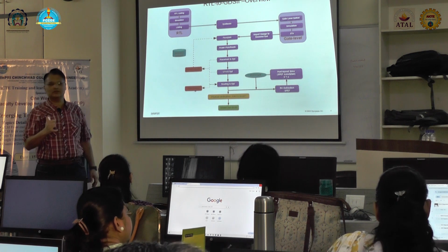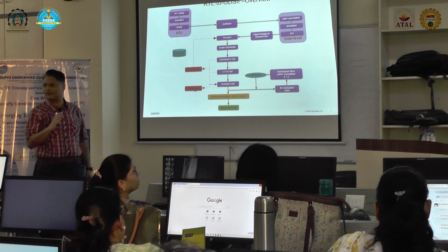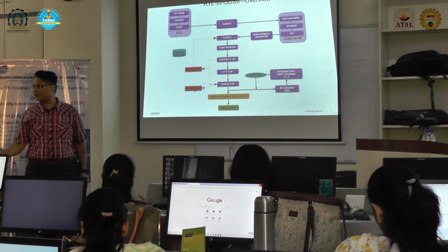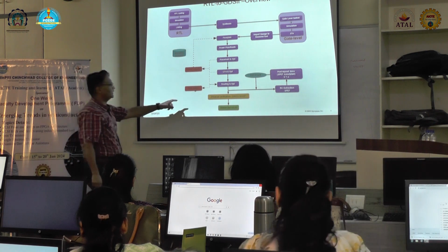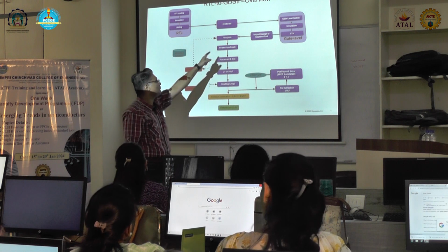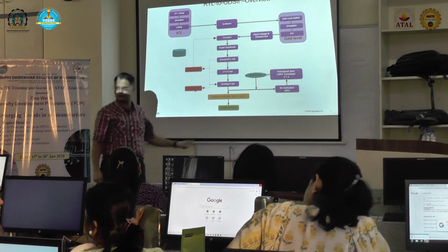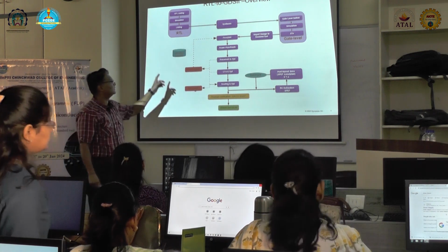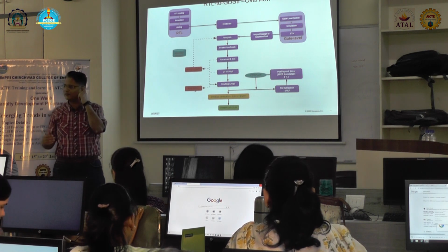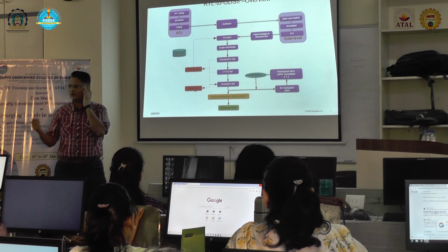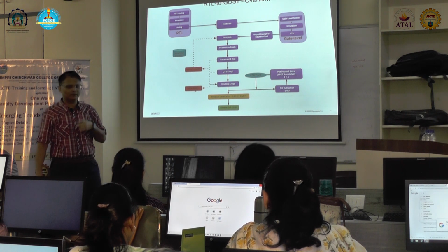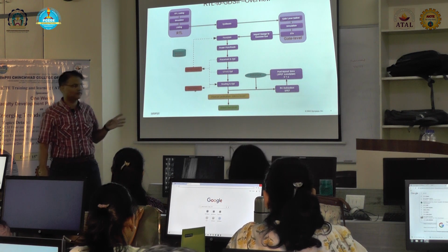That is why it is very important for you to design it in a way that it will not face problems going forward. Because just imagine you have to repeat the entire process from here, right? So let us say now 6 months have passed and then they see a static timing analysis failure, those 6 months are lost. So you have to go back again. So this loop is the biggest challenge to break.